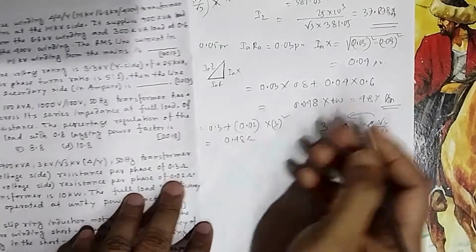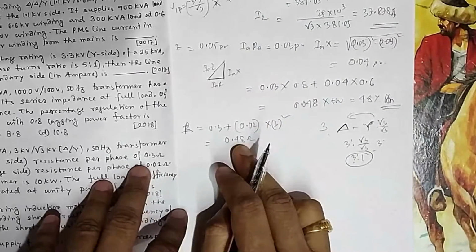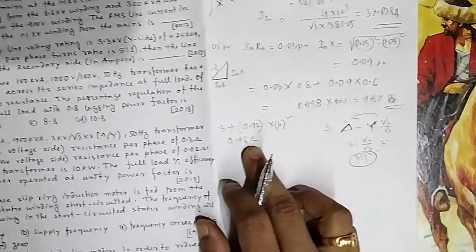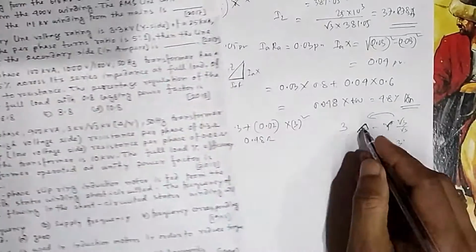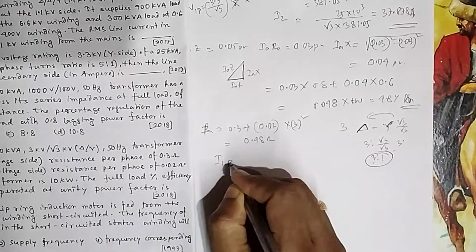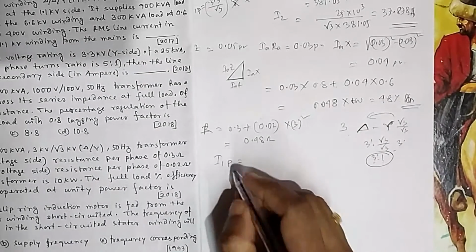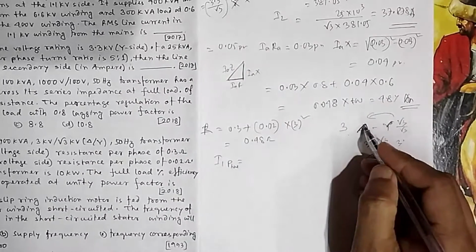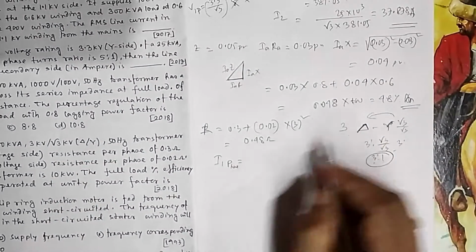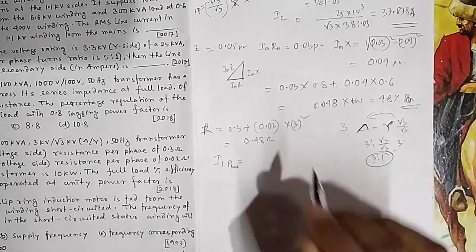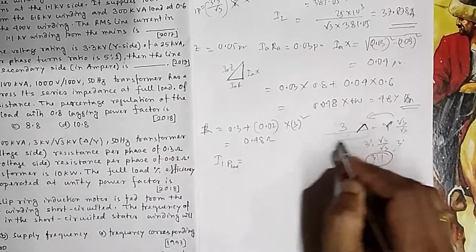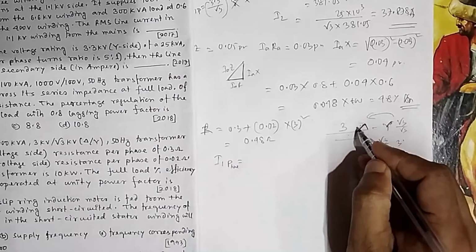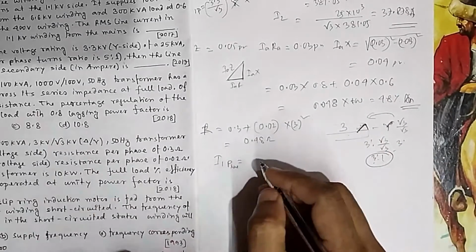So if you know this ohm, everything is primary, so you multiply by primary current. What will be the primary current? It is per phase I am calculating. That has to be careful. So on the primary side you have to calculate I1 primary per phase, because you are calculating per phase loss. Winding is in per phase, resistance is in per phase, not in line. The resistances are not connected in the line. This is on the winding, that is phase current. Through this winding phase current will flow. So you have to calculate phase current.